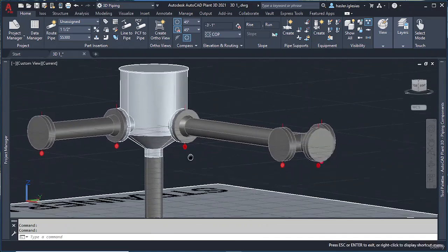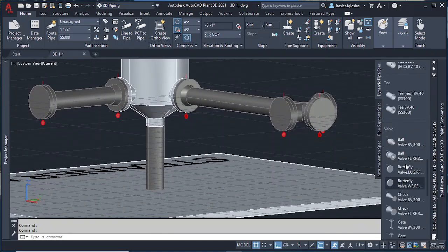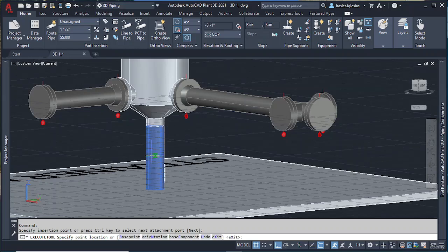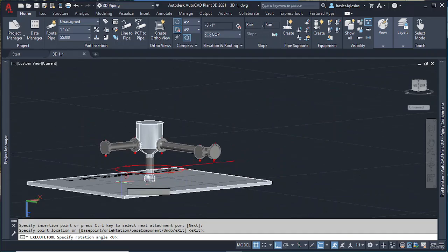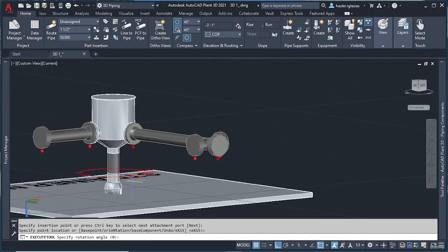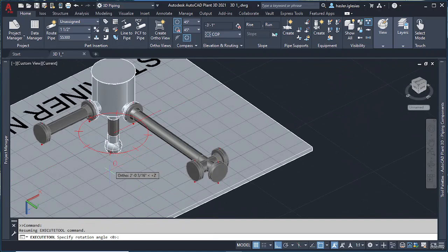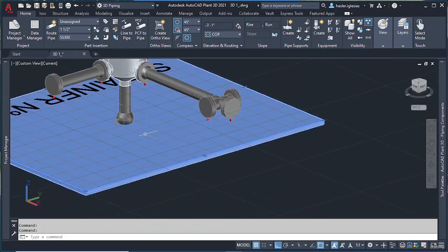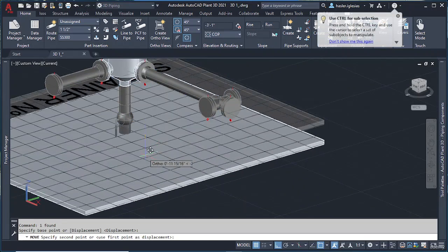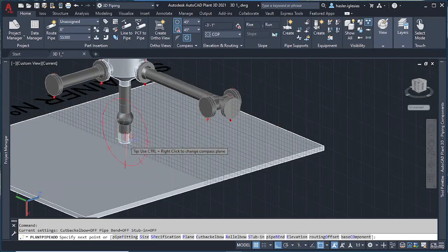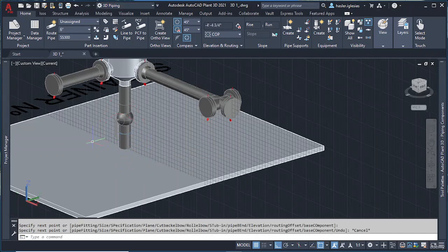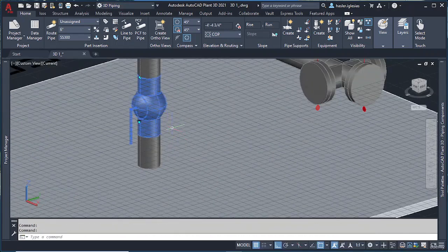Now let's put a valve here in this down part. And let's say, I don't know, a ball valve. Okay, let's put it here. Well, it's too big. I'm going to have to move the floor afterwards, but I'm doing that afterwards. Look, I can also orientate and say in what direction I want it to be. Okay, so let's say here, escape. Okay, I'm going to move the floor. Right, move, select it and move it. Okay, let's say right here. I'm going also to extend the pipe.